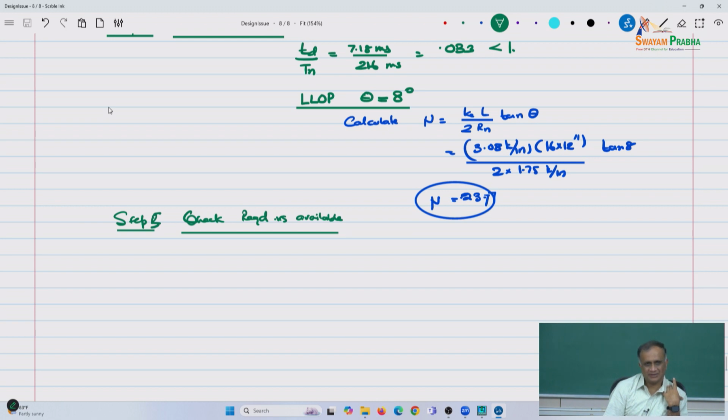We haven't addressed connection issues in even our steel and concrete. Concrete, especially at the corners, a lot of times in cantilevers or any edges, you'll have an L shape, right? Now, when you're going to blow out from inside, we are assuming a fixed support, but what's going to happen to that L section? It opens up. So that's actually not good. So connection issues.